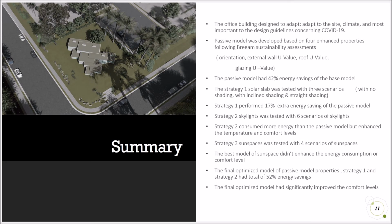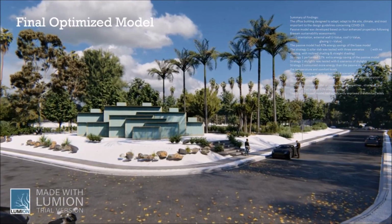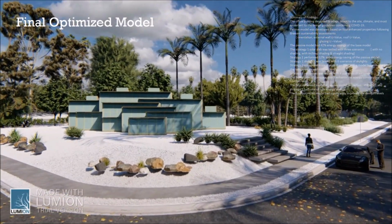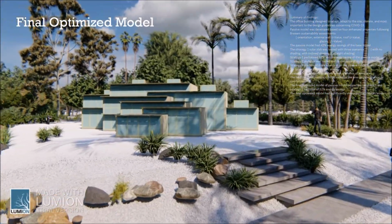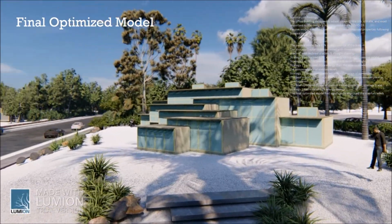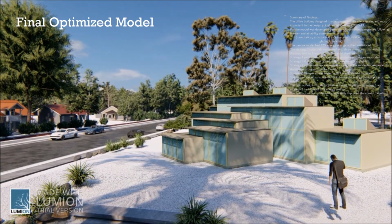As a conclusion, a summary of findings is highlighted. The office building is designed to adapt to site climate and, most important, to the design guidelines concerning COVID-19. The passive model was developed based on 4 enhanced properties following the BREEAM sustainability assessment. The passive model had 42% energy saving of the base model.